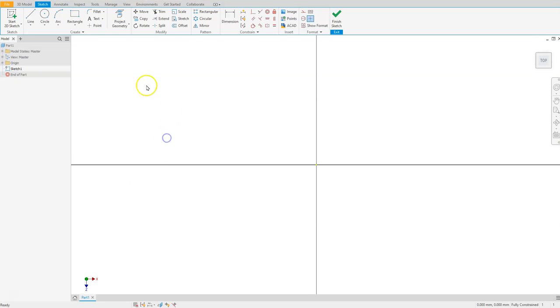Okay, so now we're in the sketch icon. We're looking at our ribbon, and it is on our 2D sketching. Let's start with a line. I'm going to click here, and once again I'm going to go down, and you can see that I got a vertical constraint being applied to this line, and I just want to get it close to 75. I can even make that about 80, so just somewhere in the general vicinity of that. I'll click here. Next I want to go over about 60, so I'm just going to go a little bit past that, making sure I lock the perpendicular.